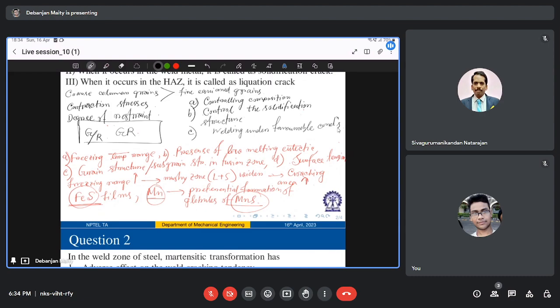And in terms of this favorable welding condition, what I mean to say is you can employ some high intensity, high energy density or low heat input process, like laser beam welding or electron beam welding, right? Those are high intensity processes where you can control the heat affected zone. Or else you can minimize the restraints, or preheat the material to reduce the stress and cooling rate for materials that form these inherently brittle phases, right?